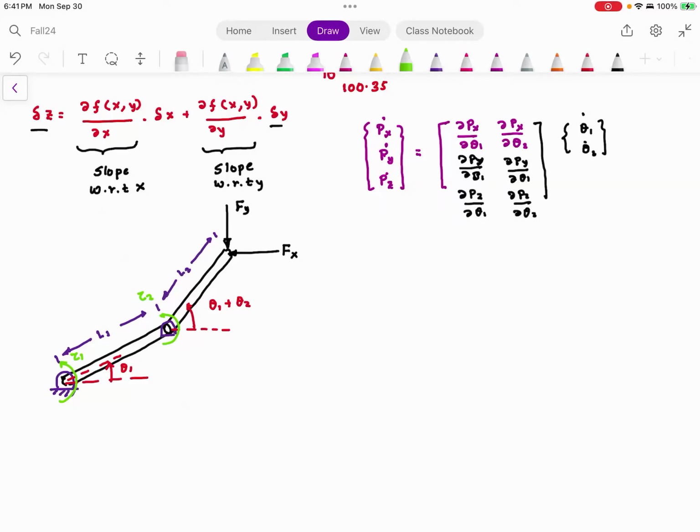If there is no torque 1 or torque 2, that robot would just fall down. Which means for that robot to maintain that theta 1 and theta 1 plus theta 2, I need to supply some torques tau 1 and tau 2. Everyone understood this? How do I solve this problem? This is called static force analysis because the robot is not moving. And this problem sets the stage for the next few chapters where the robot is going to move. So please understand, this robot is in a static position and I want to find the value of tau 1 and tau 2 so that the forces Fx and Fy are cancelled.